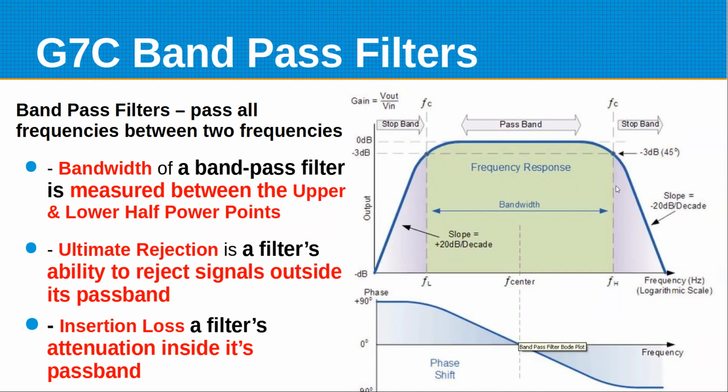They don't get into it, but another thing is you get a phase shift because these are reactive components. So it turns out that at the half power points, the phase shift of the signal coming out is 45 degrees. These two charts aren't quite synced up, but this point down here would actually be at 45.